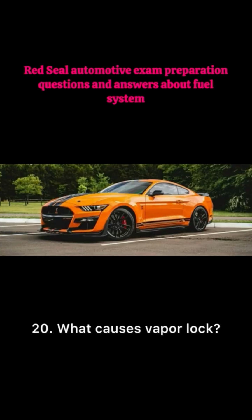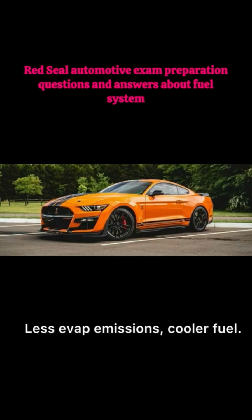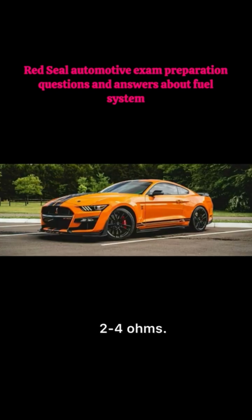20. What causes vapor lock? Heat turns fuel to vapor in lines. 21. Why use returnless fuel systems? Less evap emissions, cooler fuel. 22. Saturated injector resistance. 1-2 ohms. 23. Peak and hold injector resistance. 2-4 ohms.